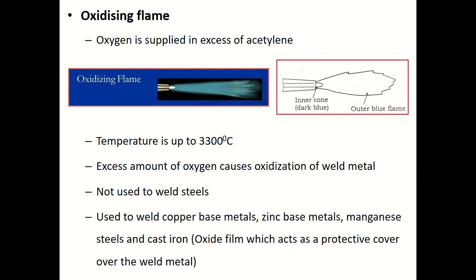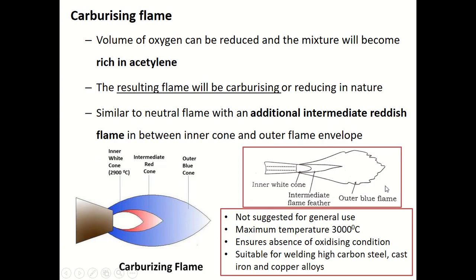Another important flame is a carburizing flame. In this case the volume of oxygen is reduced and the mixture becomes rich in acetylene, and as a result the resulting flame will be carburizing or reducing in nature. It is similar to the neutral flame but with an additional intermediate reddish flame.